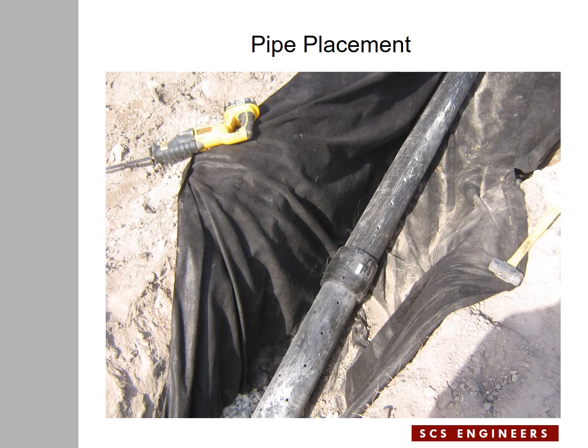The geotextile goes in, directly sits on top of the composite, and the perforated pipe gets installed inside the trench. You don't really need gravel below the pipe to protect the pipe because the surcharge loading is very small. So we put the pipe in the trench directly above the geotextile, and then the gravel goes in the trench.